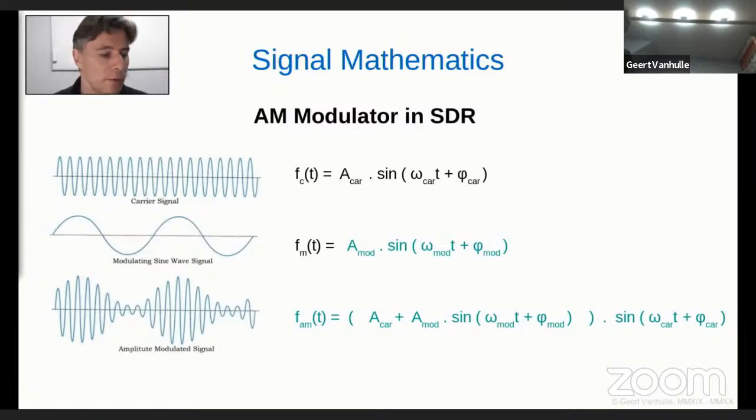In general, they will use tables for that, because if a sine wave actually has to be calculated, that's even a lot more calculations. They will use tables with pre-calculated angles. Of course, this has a compromise on the accuracy of it. But even that will take some CPU load. So we have a lot of CPU load if we would like to do that.